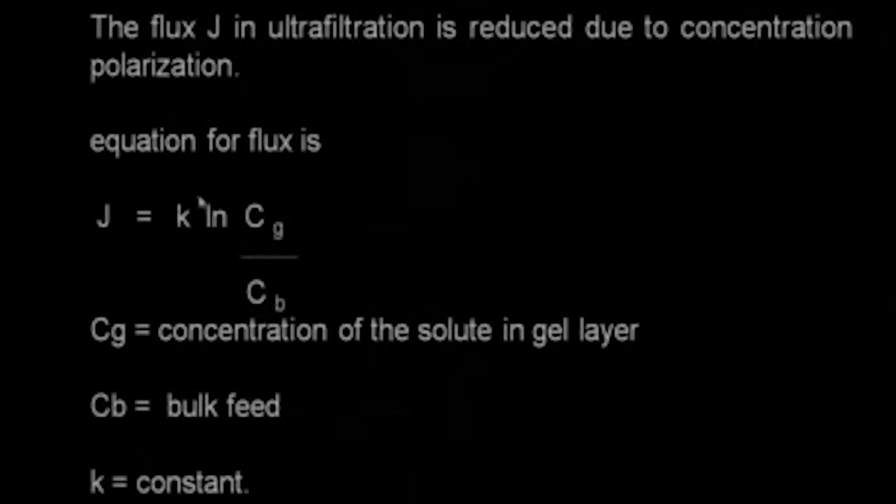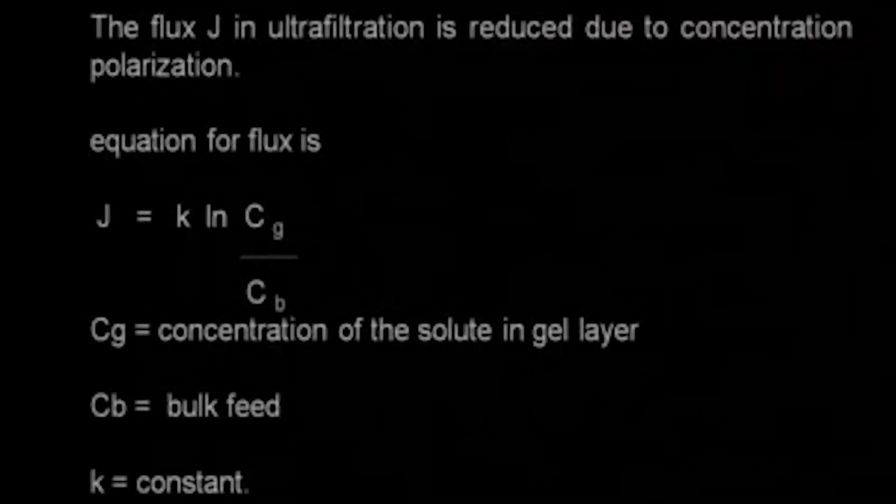So K is your constant, and now here you see J is independent of the pressure drop. So the pressure does not come into the picture in ultrafiltration, whereas in microfiltration pressure plays an important role. It is almost like a normal filtration. You see the difference? Okay.